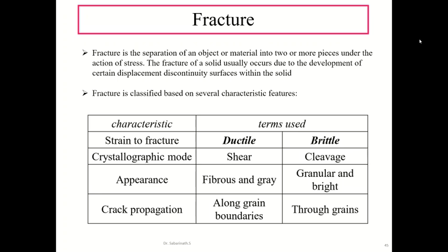Fracture, as I said, is a fundamental type of failure. When load is applied, the body will separate into two or more pieces. So fracture is the separation of an object or material into two or more pieces under the action of stress. The fracture of a solid usually occurs due to the development of certain displacement discontinuity surfaces within the solid.